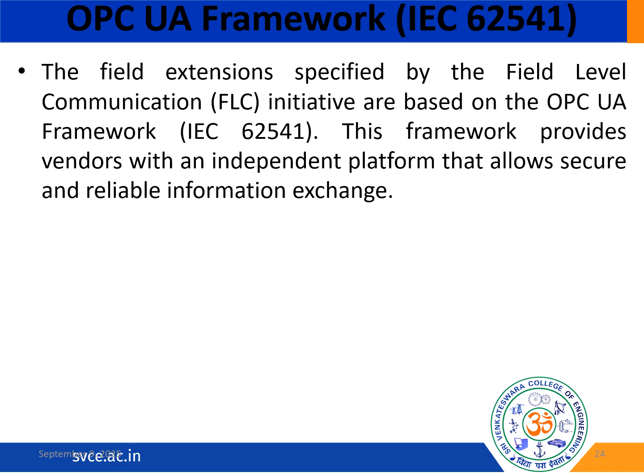Next, we'll continue with the OPC UA framework. Here the field extension specified by the field level communication initiates the OPC UA framework, that is IEC 62541. The OPC UA framework supports client-server services, and it also supports publish-subscribe models and protocols.